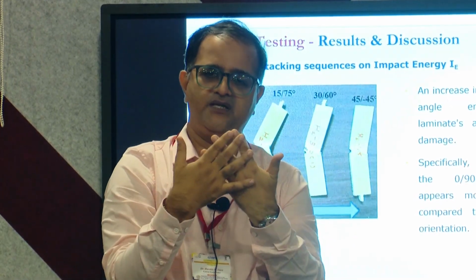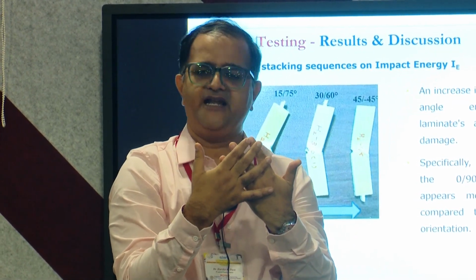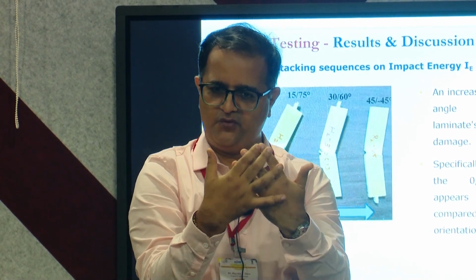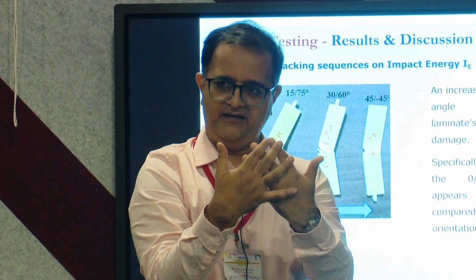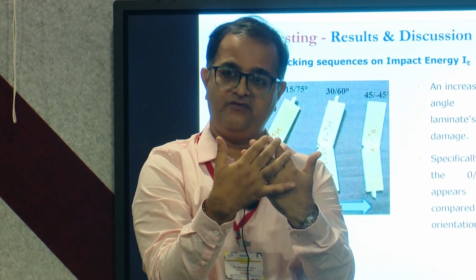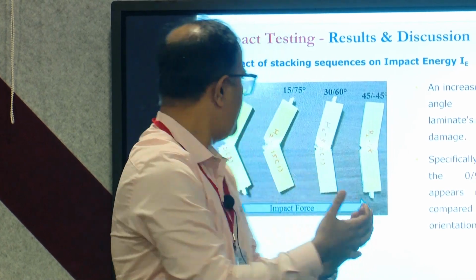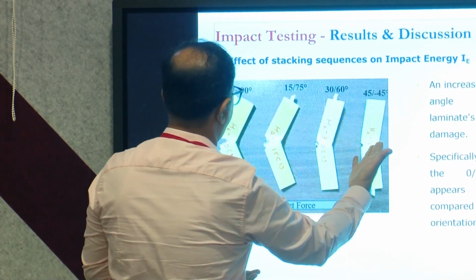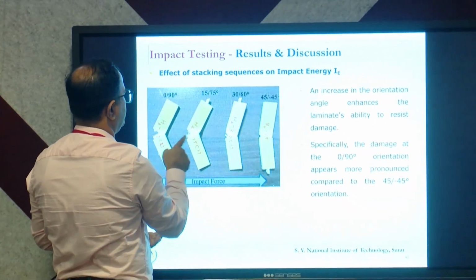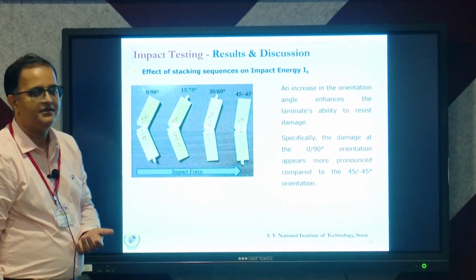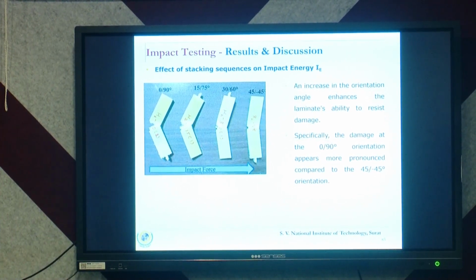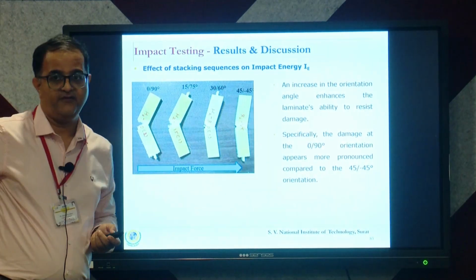When it is 45 plus 45 minus 45, they take time to decide who would fall first, me or you. They will take time to decide who would break first. So in that, the amount of energy that it absorbs would be more, so it will not break that easily. It may come under the effect, but it will not break the way 0-90 or the nearby inclinations would break. Okay. So in impact, 45, yes.